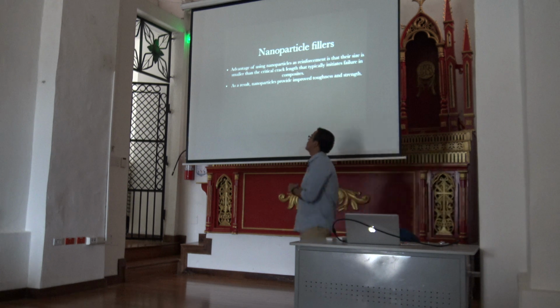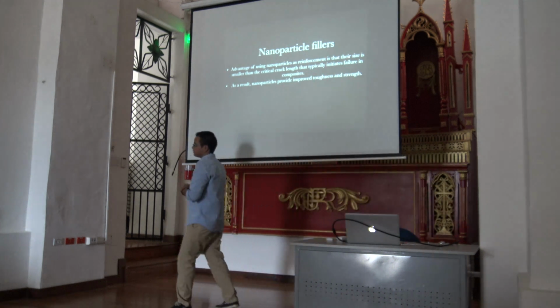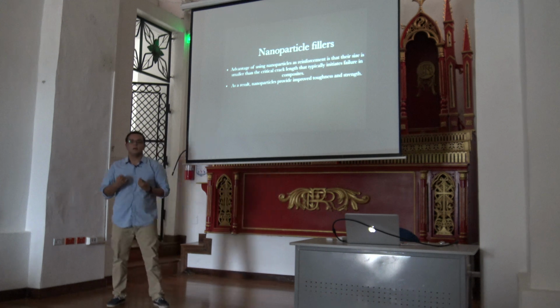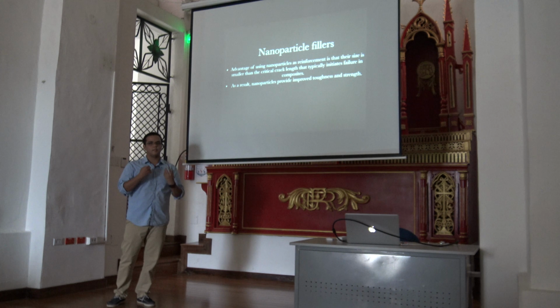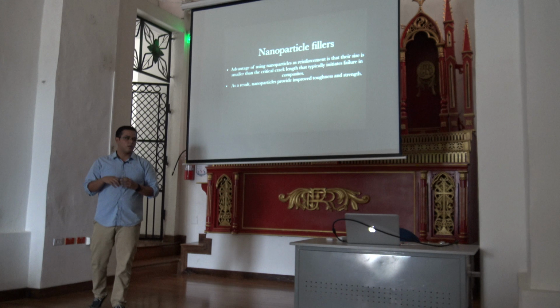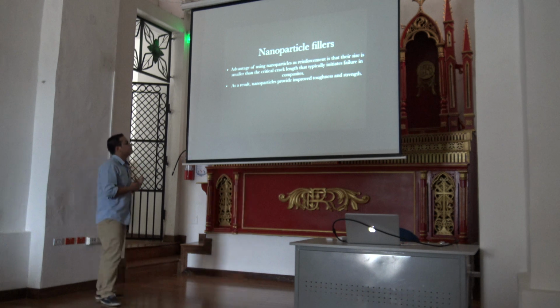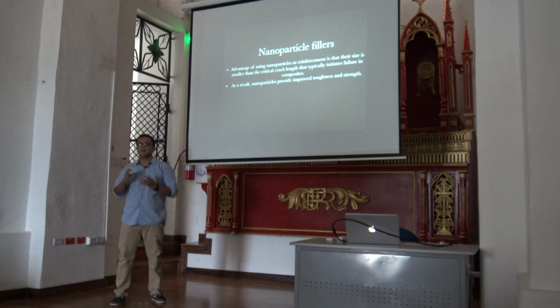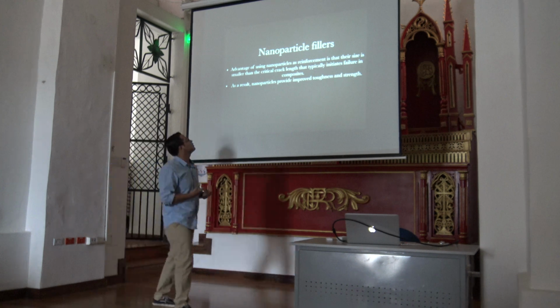So the nanoparticle filler's importance is related to its size and how it's distributed, because the properties of the polymeric nanocomposite will be affected by the quantity of these nanoparticles.